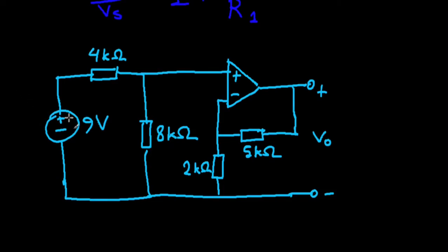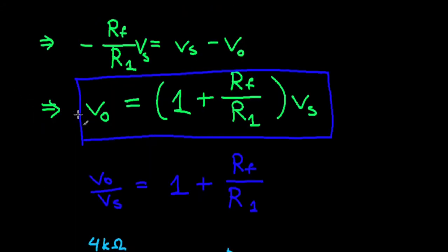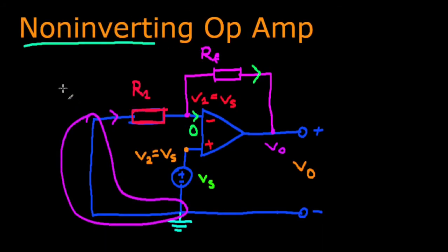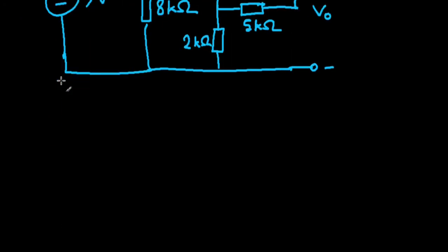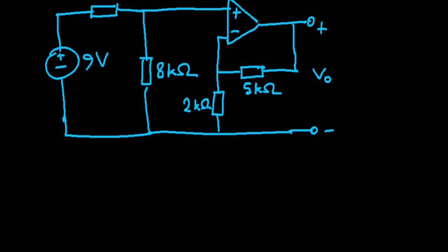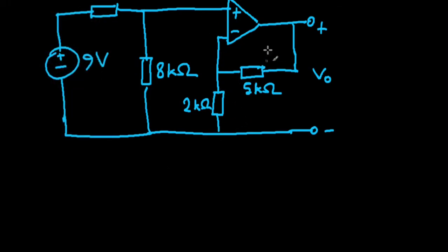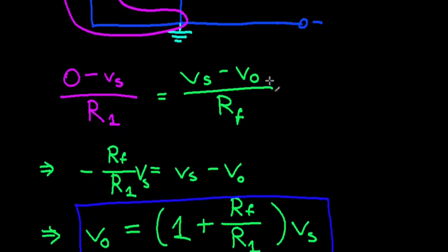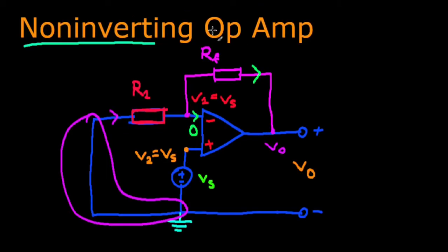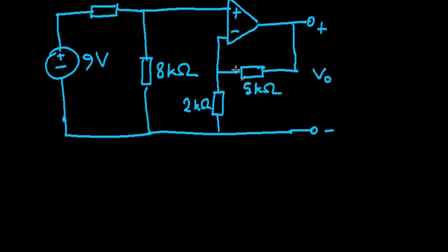At first glance, this doesn't look very much like our non-inverting op amp, but let's consider some things. The first thing I'd like you to notice is the things at this end, the inverting input. The configuration is the same as here, just drawn a bit differently. It's pretty clear that this is your feedback resistance, slung over the op amp, and then you have this connection with the inverting input.